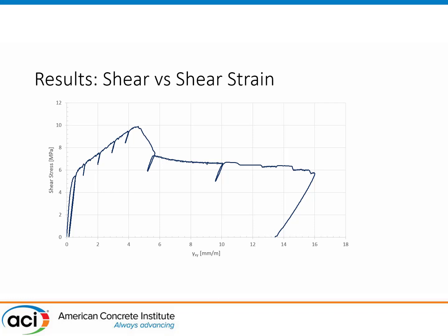Ultimately, up at 10 megapascals of shear, one of the cracks got too wide, as we saw, and it opened up. The unloading curve down here happened over about 10 seconds, so it was under control the whole way. And that was basically pull out of the individual fibers. So that specimen had failed, but we said, let's keep on going to see what happens. And we ended up having a very long yield plateau, I don't know what to call it, basically going out for a long distance afterwards. The strength of the reinforcement inside was about 4 megapascals by a plasticity model.